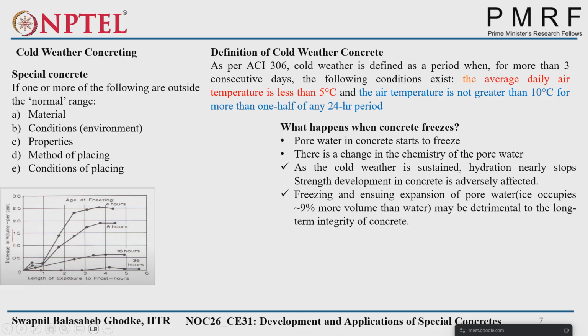Although we kept it in proper curing conditions for 4 hours, after that it still has a large concrete volume increment due to the increase in water volume. But if you keep it for 8 hours, that volume increment is a little bit less. If you protect it for 16 hours, the volume increment is more or less negligible. And if we keep it for 36 hours, there is almost no effect of the freezing condition.